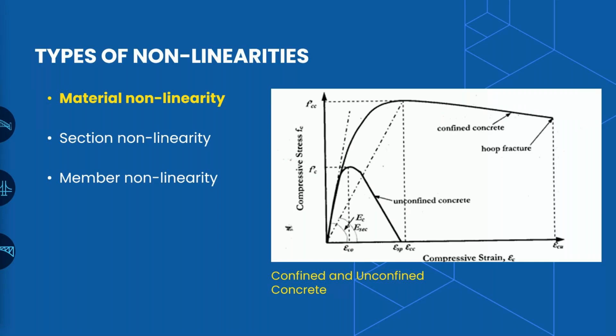We have also seen that it is not the strength which has the higher say, but the ductility. We can say that 80% of the structure's energy dissipation depends upon the ductility rather than the strength, and only 20% can be governed by the strength. So the more ductile the structure, the more the energy dissipation, and the better the performance.